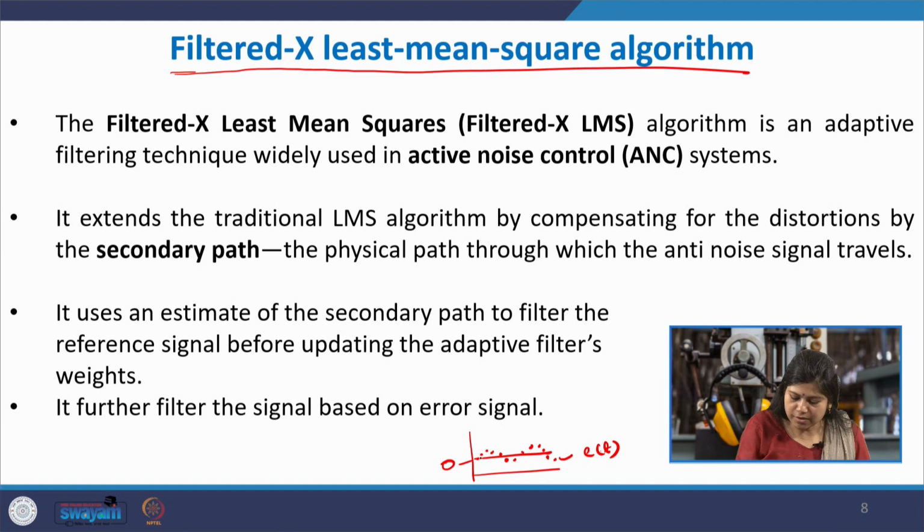This is our expected graph, but we are getting some error e(t). So, this is the true value of e(t), and this is the actual measured e'(t). You want to minimize the difference between the expected error signal, which should be 0, and the actual measured error signal, which is not 0 but some value.